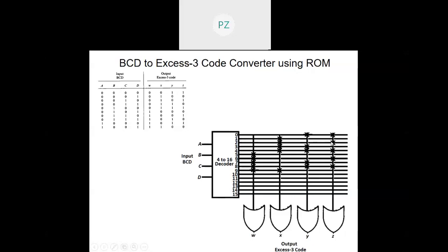This is one way to represent a ROM. It is called the line diagram, wherein we draw crossing lines, and wherever we put a cross, that means there is a connection, right? Essentially, there will be 16 inputs in every OR gate, one from each of those minterms.